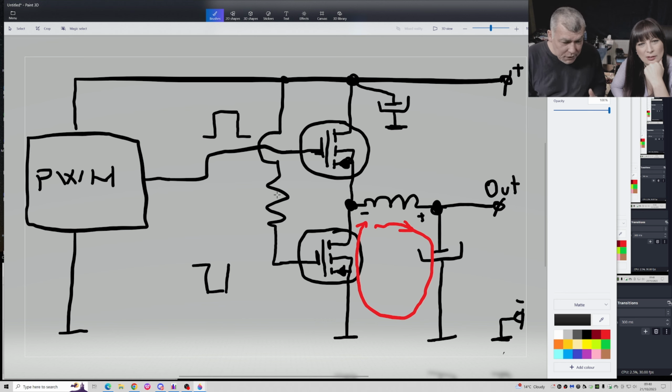First, let's assure this MOSFET can be on. Now that MOSFET is always on, and now you have to use something else to switch it off. Use another resistor to ground, so you create a divider. So you will not have 12 here, you'll have 5. Oh, you solved nothing. True.